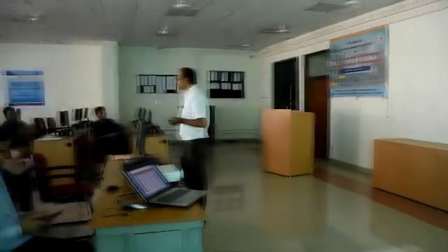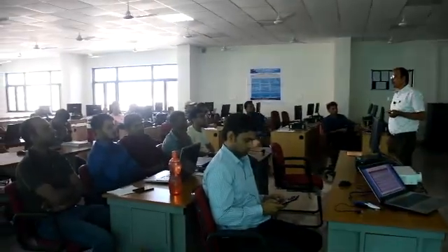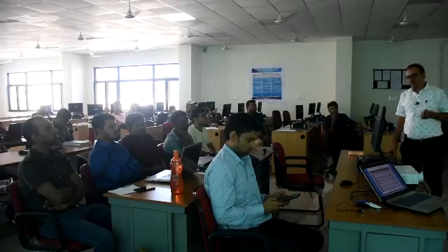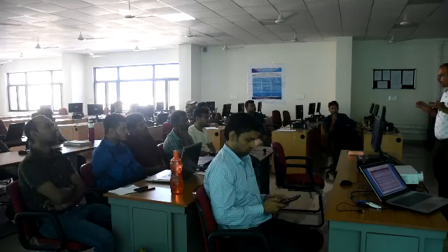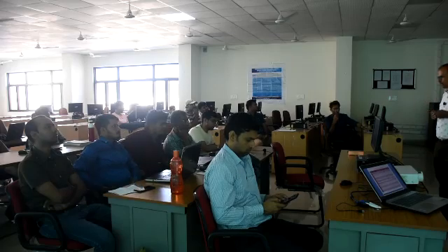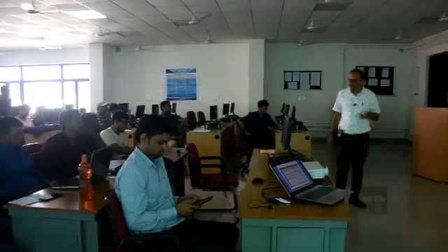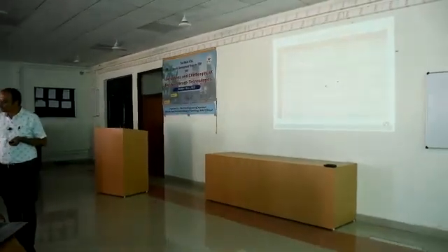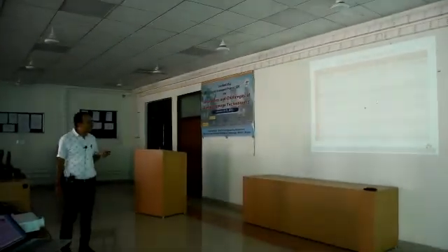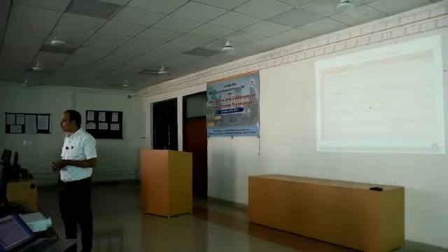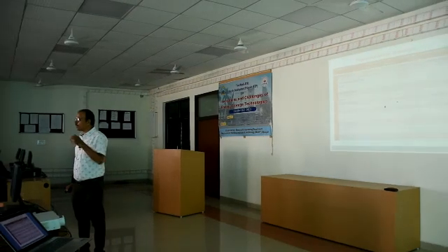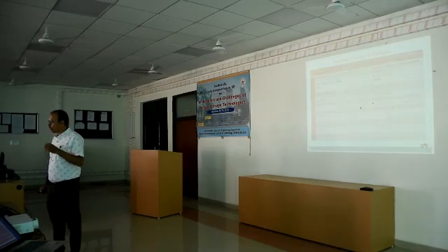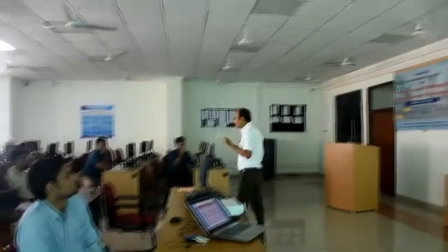Now come to the technologies available for energy storage systems. Okay, so we have classified them in three broad categories. This is storage technologies, and based on this we have the different options. So here in this table, some of these technologies are listed. Start from your capacitor, which further enhances to the supercapacitor. Okay. Then you have superconducting magnetic energy storage systems. Then you have a flywheel which can also act as an energy storage system. All these are categorized as short-term energy storage systems because they cannot store a very big amount of energy. They can store a small amount of energy which can be delivered to the grid in due course of time.